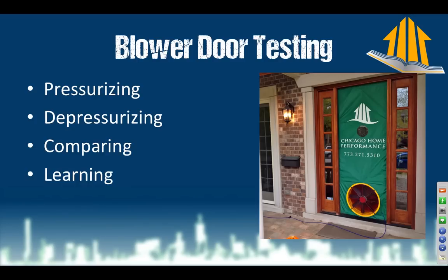So you can start to do forensics on things you can't see, touch, anything. They're in the middle of the building with these extra advanced diagnostics. And we're going to be able to prepare for advanced leakage quantification with pressurization testing, which is the one that most people don't do, because in some cases you do not want to suck air from a zone into the house, because it's just not going to be healthy. There's going to be insulation or dust or whatever.